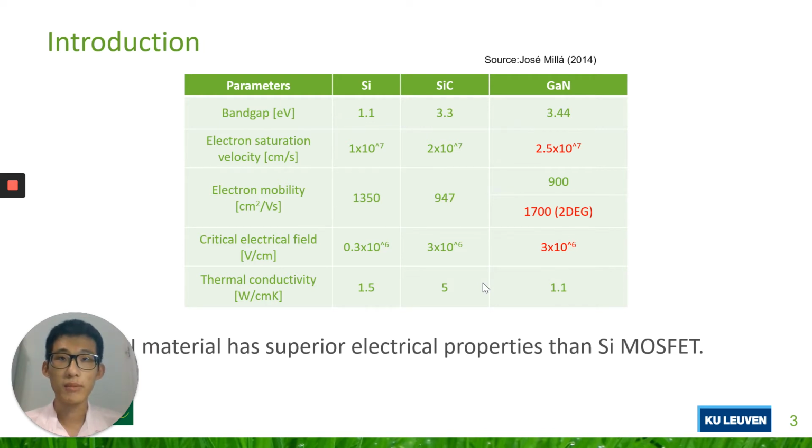It's better for a power device to have a larger breakdown voltage so that we could operate at a very high voltage. And last is the thermal conductivity of the gallium nitride. Though it's lower than silicon carbide, the device could be packaged into a flip chip or have a chip-scale structure. So in that way, it could also achieve a higher heat dissipation.